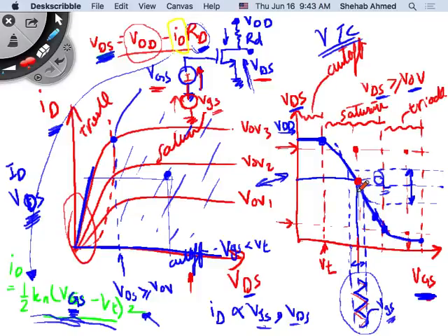If this is a DC value, this is a small signal, an AC signal, for example, above and below your DC operating point. So your DC operating point really defines where you operate, right? And then your small signal is on top of that. Now, if I keep the small signal the same, but I bring my DC operating point here, fine, it is linear here on top, but here I'm starting to hit what?